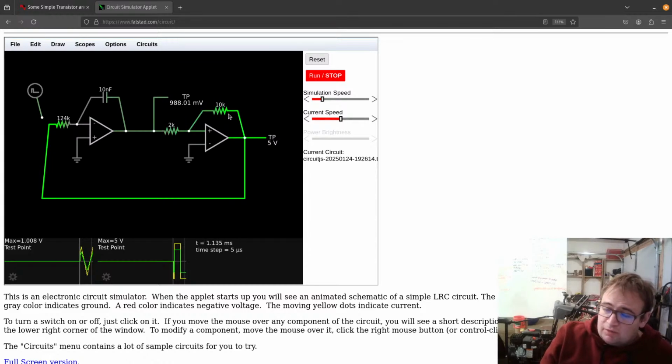Now, when it's just under minus 1 volt, that means something just under minus a half milliamp will be flowing this way, and that will cause a positive voltage to have to be here, because we will want a larger voltage drop across this 10K, and that's going to again change the voltage to there. Let's go.